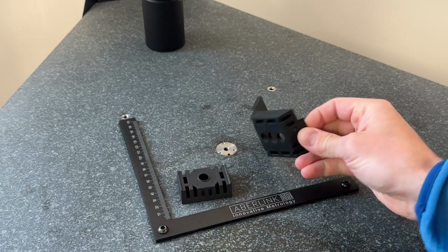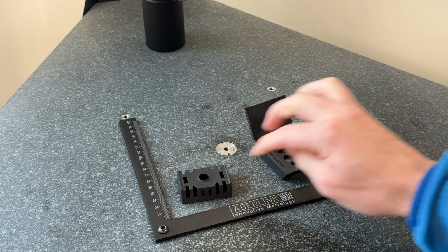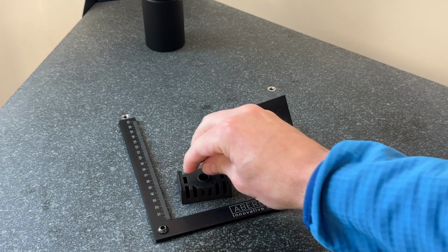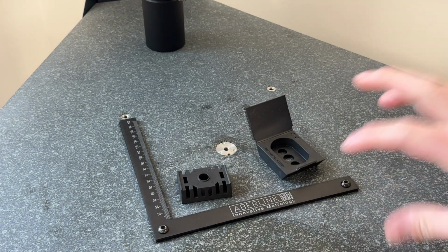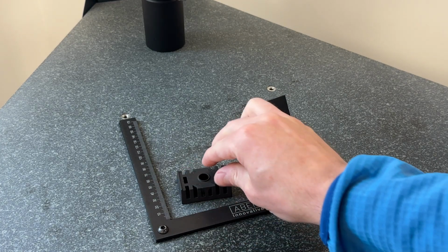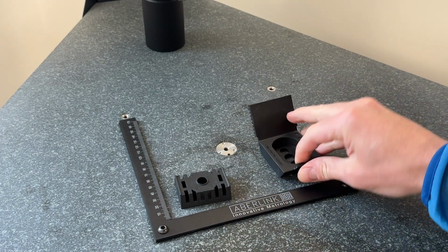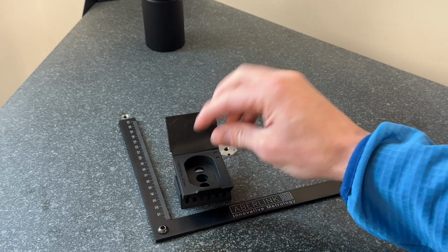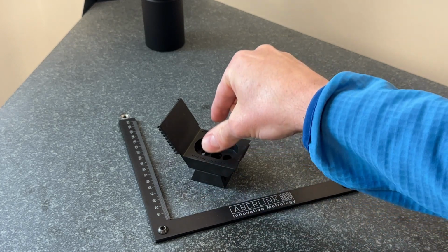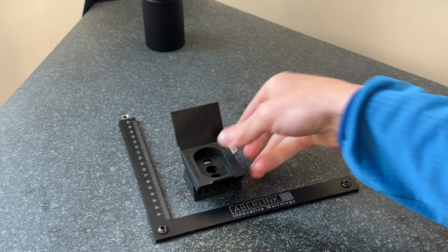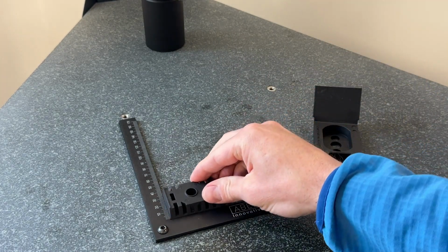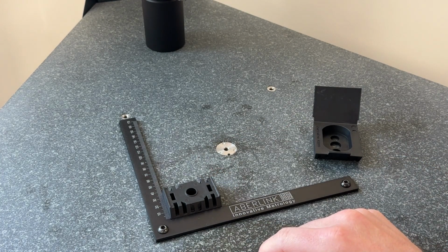Now obviously we could try measuring this face and this face in two separate operations, but given the material being slightly softer, it's a plastic rubber style part, I can't take points on every single bit of the surface for both parts. So getting the size where the two parts mate together, i.e. this height from the table to here, as it would operate in the real world, requires a measurement with both parts together.